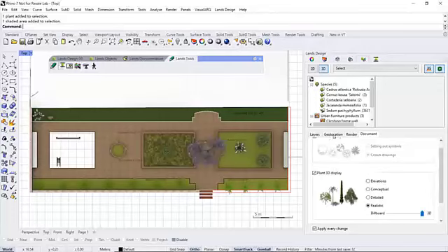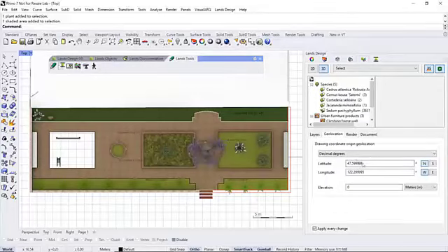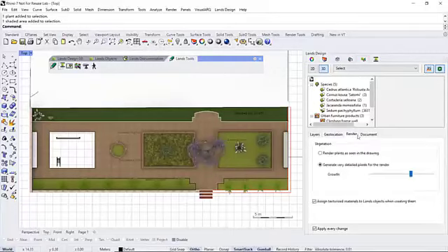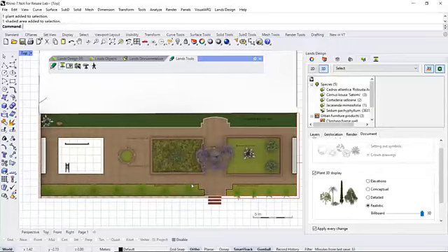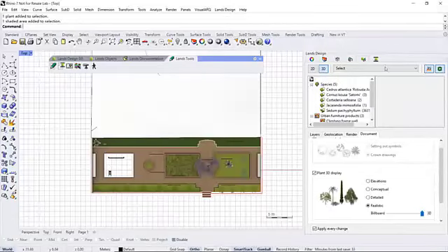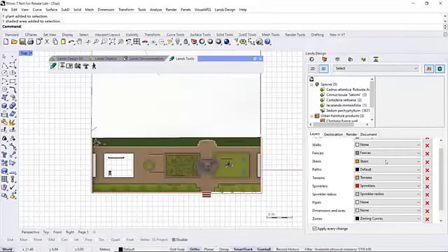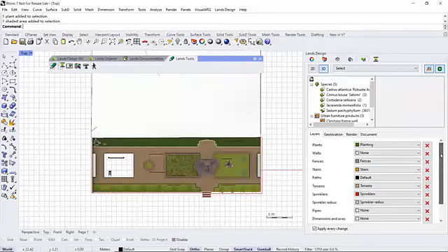Also, this document is geolocalized. This is taking the geolocation based on the Rhino document. Of course, we can change that. And from the edit panel, you just manage all these document parameters. Also, you can define in which layer the new objects are located when you create them.